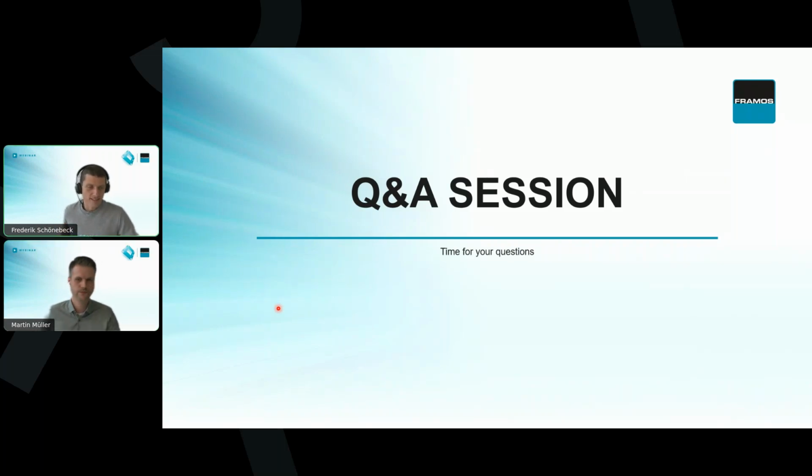Thank you, Martin. Great presentation. Yes, it did trigger a couple of questions. Let's just start already with the first one. Binning, you mentioned binning is happening also in phones. For CMOS image sensors, is it right to assume that the binning actually happens already in the charge domain, like for CCDs, or does it only happen later?